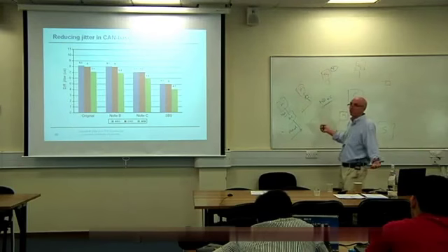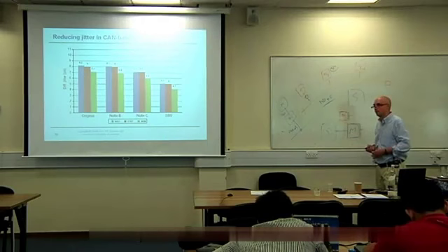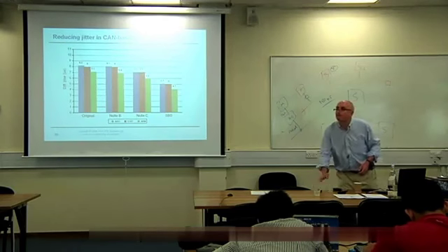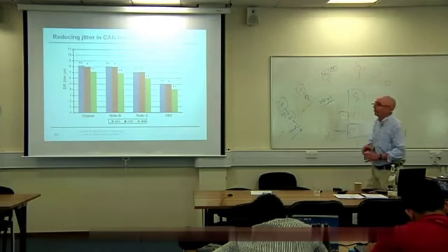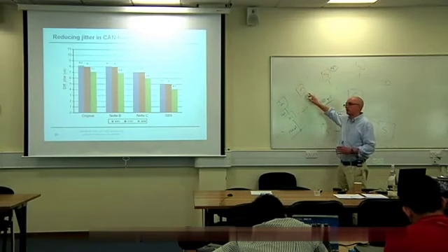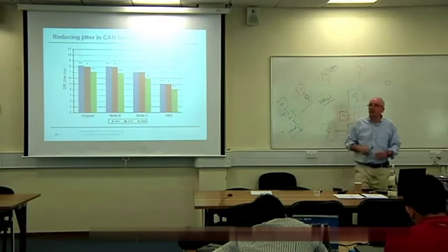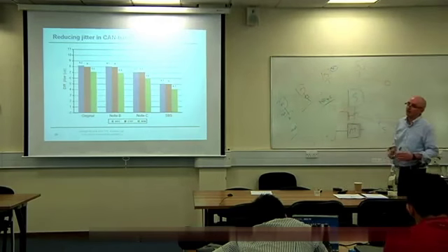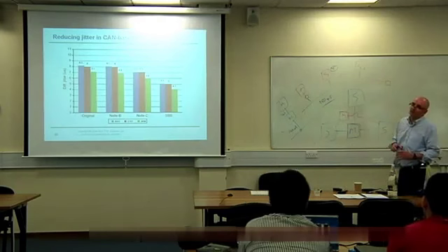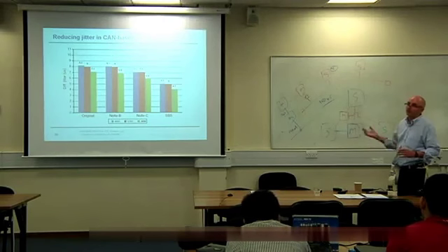You can change the protocol, but that's even more expensive, because then you'll have to do a lot of work on that. Will the problem still exist while the data is being communicated between the slaves? No, because the thing that's driving the scheduler is the messages from here. So it doesn't really matter if there's a little bit of variation in the messages going the other way. We've got about 24 microseconds variation in the duration of those messages, but we know what the worst case execution time is, so we can handle that.